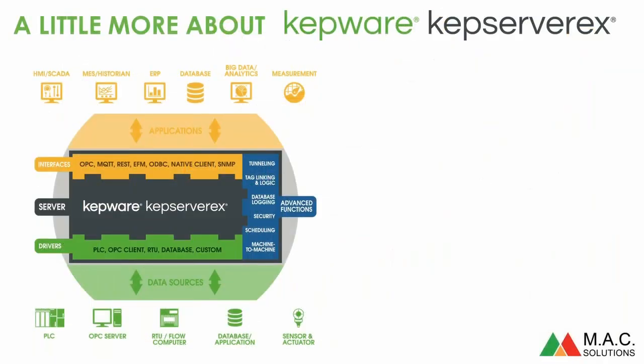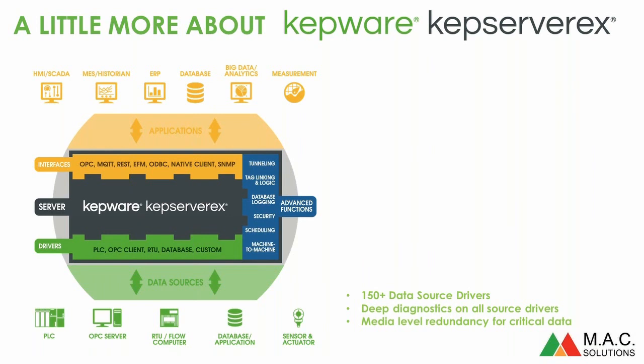Okay, so a little bit about the software itself. On the south side, on the device side, there's over 150 device drivers. I think I've mentioned it. All of those have very good diagnostics. There's a diagnostics menu you can turn on, and you can filter the diagnostics very finely to get down to the diagnostics just for a particular device, even looking for a particular type of packet, if you like. So that's very good for fault finding if you're doing any comms and having issues getting the response you expect.